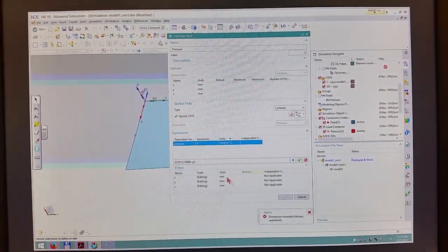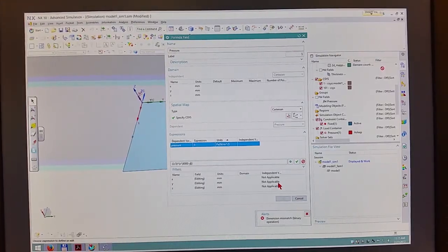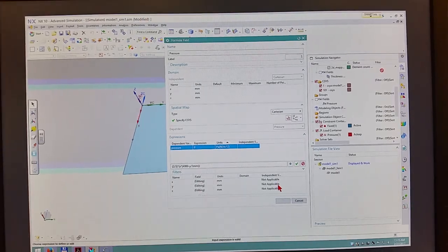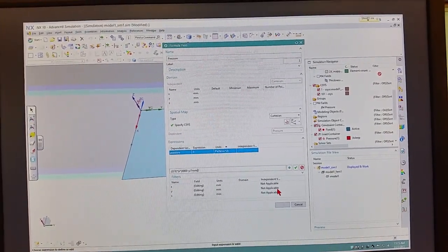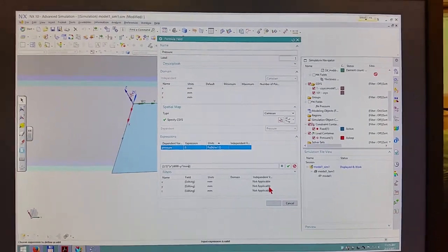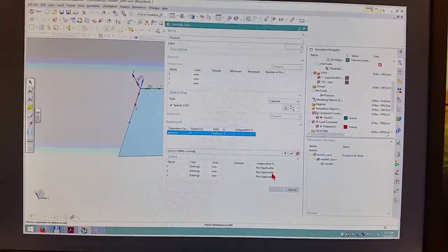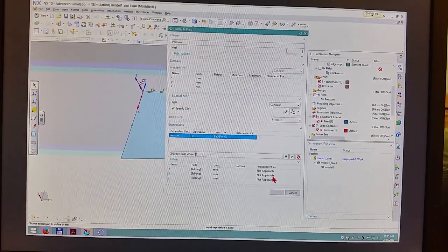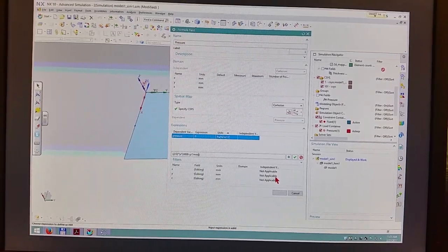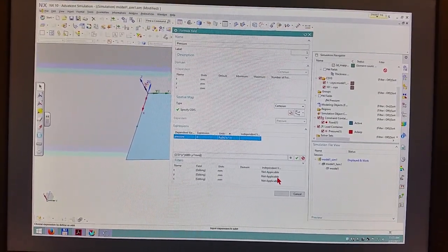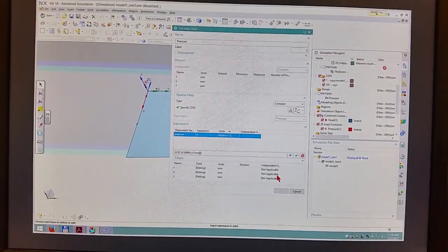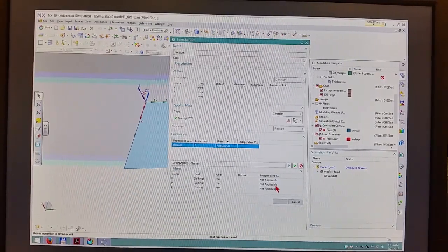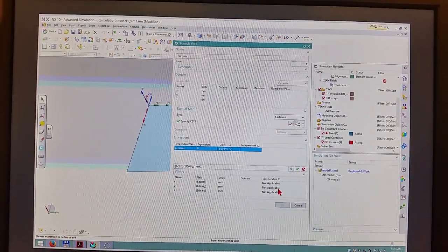I'm gonna take this y and divide it by 1 millimeter. If I just put mm, it's thinking I'm gonna use the variable mm. If I put 1 mm, then it's reinterpreting that as 1 millimeter. So I have millimeters divided by millimeters, right? So now I can do the 4,000 minus y. Now I said this should be all unitless, so what's the other problem I have? Do the same thing for x.